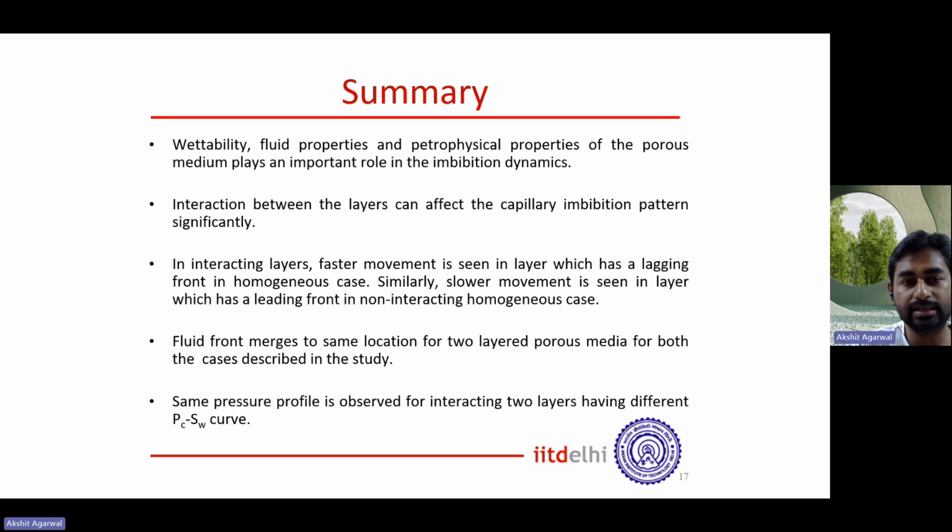In the interacting layers, we see a faster movement in the layer which has a lagging front in the homogeneous case. Similarly, we see a slower movement in layers which have a leading front in the non-interacting homogeneous case. The fluid front merges to the same location for two-layered porous media for the cases that we used in this study. And the last one is the same pressure profile we observed for interacting layers for different capillary pressure curves.